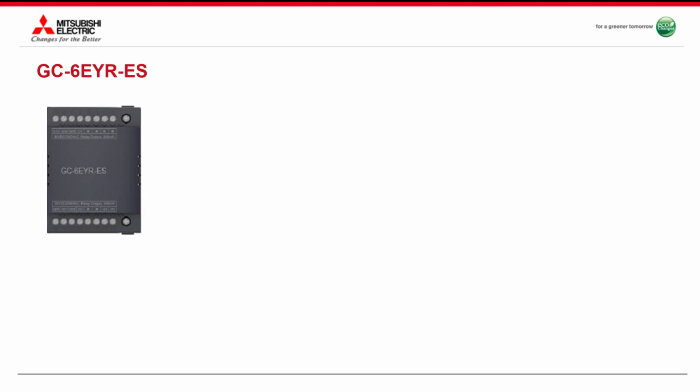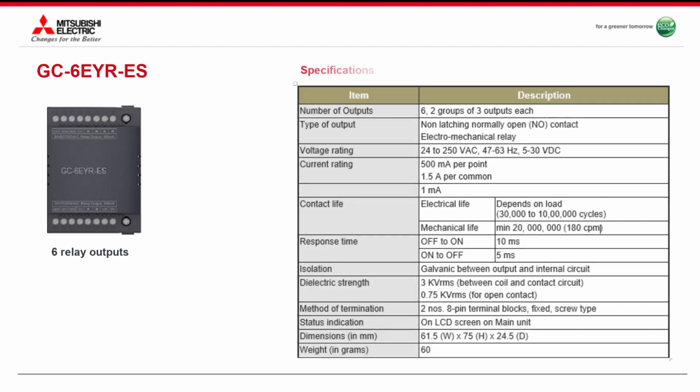Second module is GC-6EYR-ES. This module provides 6 relay output points. You can add this module in I/O extension slot 1 or I/O extension slot 2 or in both I/O extension slots as per requirement. These are specifications of the module. Module provides 2 groups of relay outputs. Each group can provide 3 relay outputs.